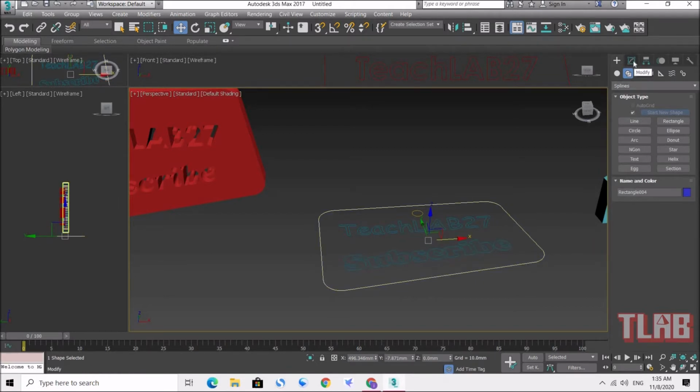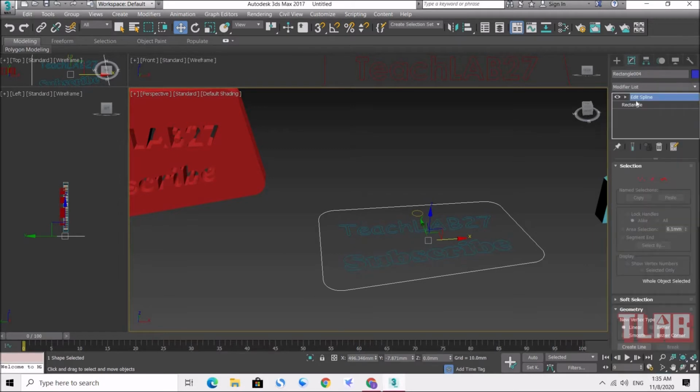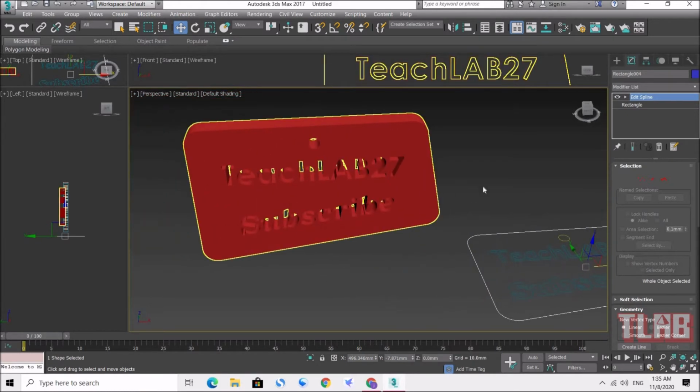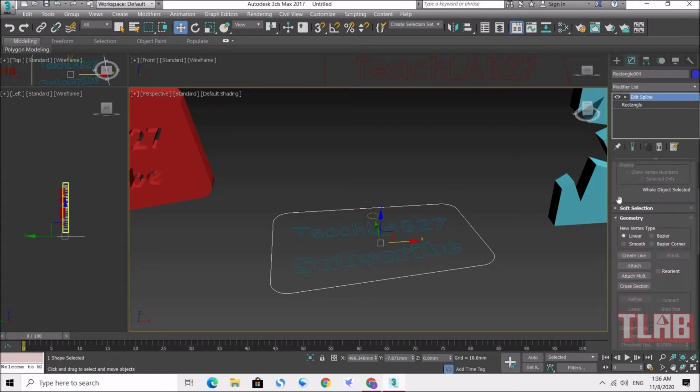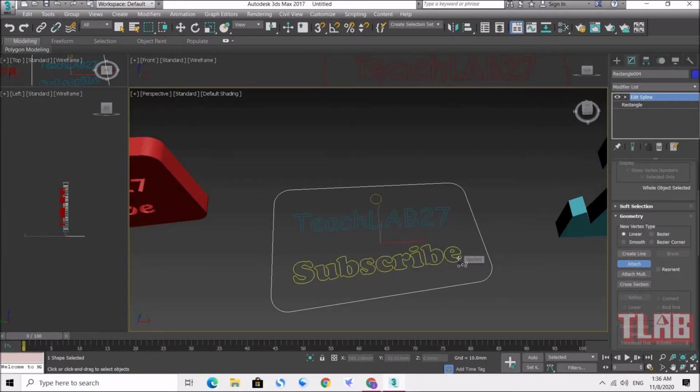And then you need to go to the modify list. Because we already have this spline, if you want to complete it like this, you need to select one of them to set up and add the other splines inside. There is one setting called attach. Attach means combine. So we need to use this one. Click and then move, click one by one. That means combine together.